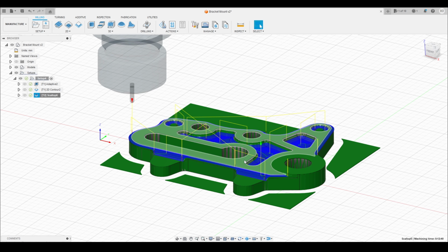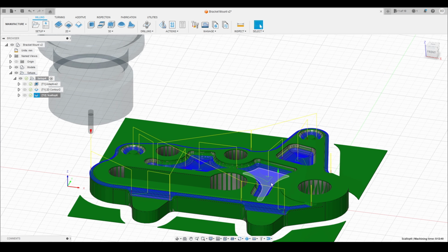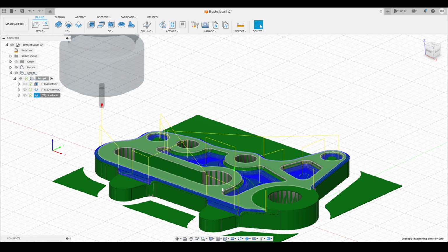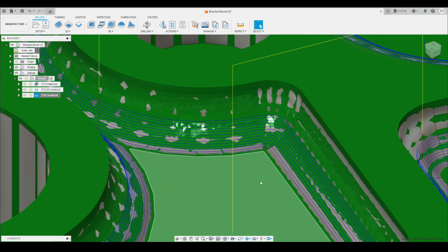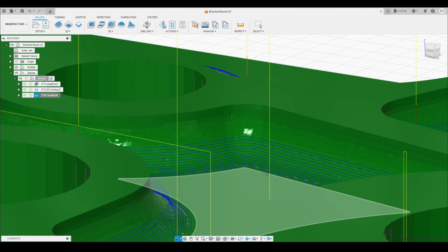So that's a pretty fun toolpath to play around with. It can apply itself to some pretty complex geometries. It could do circular faces. It could do complex angles. It can do these radiuses, obviously. It does a lot of work for a simple operation, and it can achieve a lot with just a single tool. These step overs can be adjusted to increase your resolution.